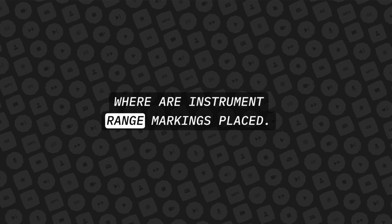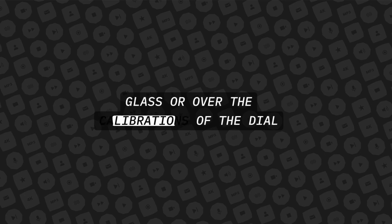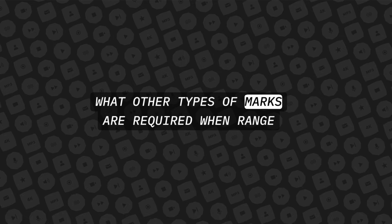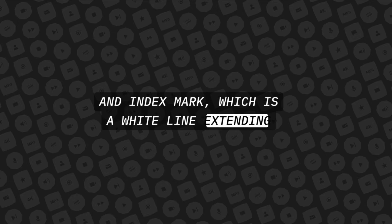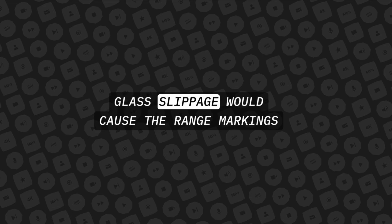Where are instrument range markings placed? They're applied to the outer edge of the cover glass or over the calibrations of the dial face of the instrument. What other types of marks are required when range markings are applied to the glass instrument cover? An index mark, which is a white line extending from the glass cover to the instrument case to indicate slippage of the glass. Glass slippage would cause the range markings to be in error.